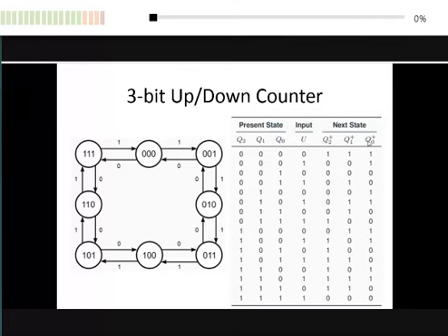You don't waste time doing the K-map. As your state table gets larger, it's easier to make mistakes, isn't it, in K-map? But if you transfer this state table directly using multiplexer, it's hard to make mistakes unless you are really lousy. If you are sleepy or unwell, that's a different story. Okay, it's hard to make mistakes, especially Q2. Q2 here, you look, it is next to the border of the inputs, so cannot make mistake.